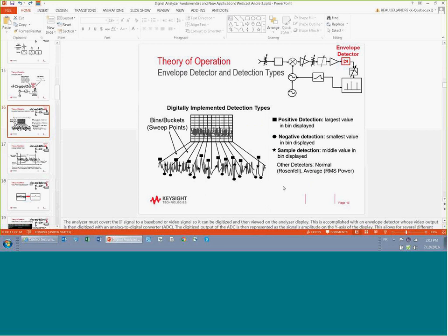To find out, depending on the board you're using, the IF digitizer option you took, the digitizer might digitize at 400 megasamples per second, and depending on the number of points you took and the resolution bandwidth, the sweep time will be slower, and the number of points captured will vary. The 4001 is the maximum number of points you could display, and in some cases it might be the number of points that were captured, but usually it captures more than that.